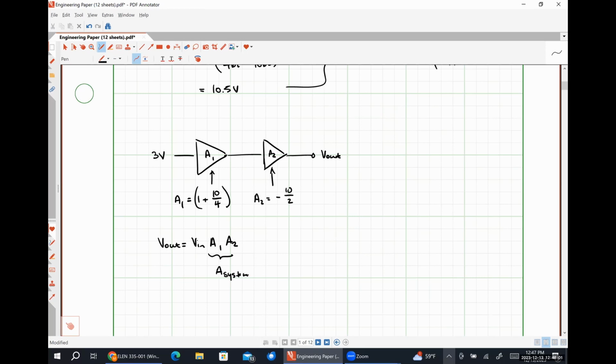We could take the difference of two signals and then integrate that output by cascading a differencing amplifier into an integrator, cascading a differencing amplifier into a differentiator, or we might want to take the integral of a combination of input signals. But it's all just simply putting the stages in the order that we want the mathematical operations to occur, right? So this is very, very boring because it's just scaling twice, and we could have accomplished this with a single amplifier, but I was just trying to show you how it worked.